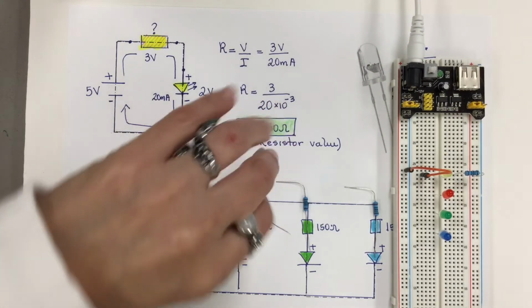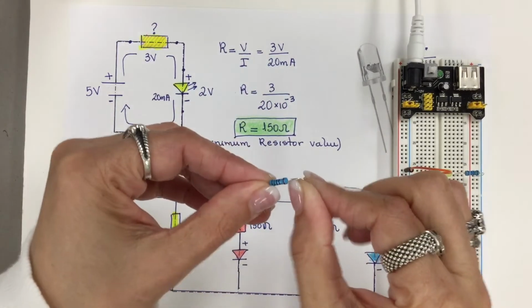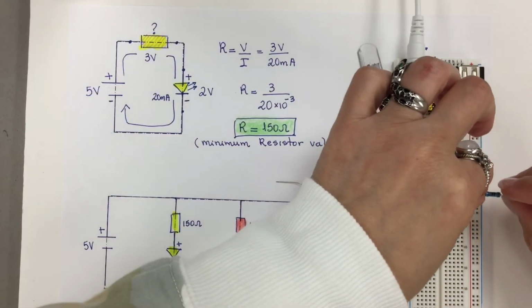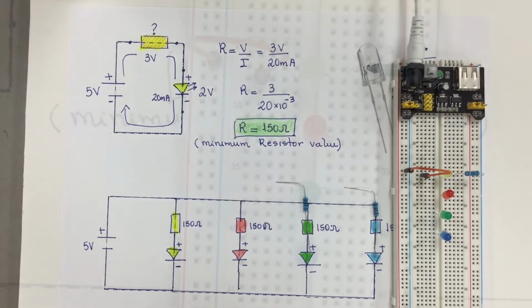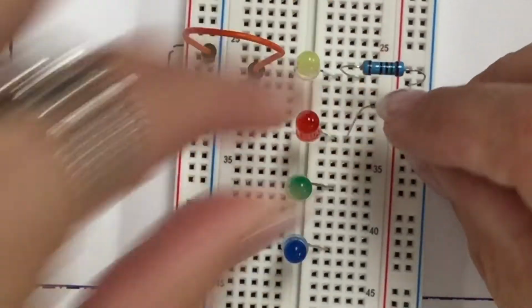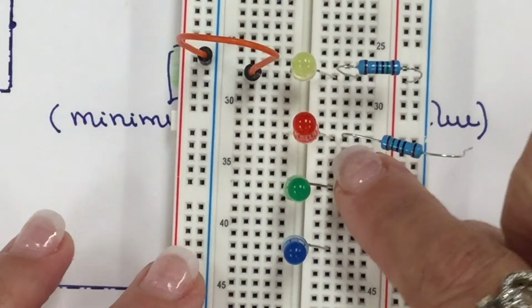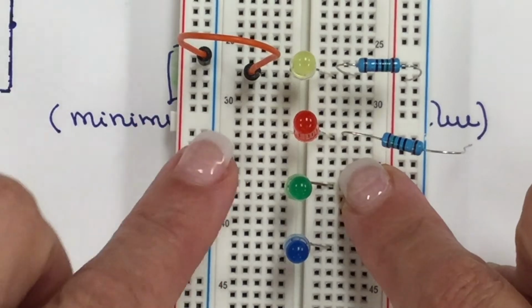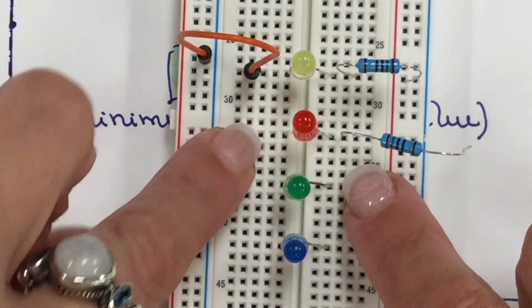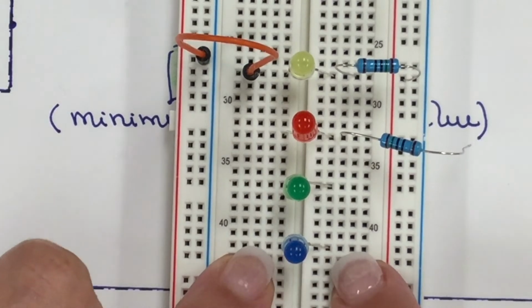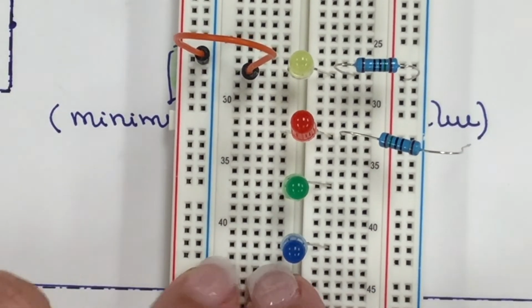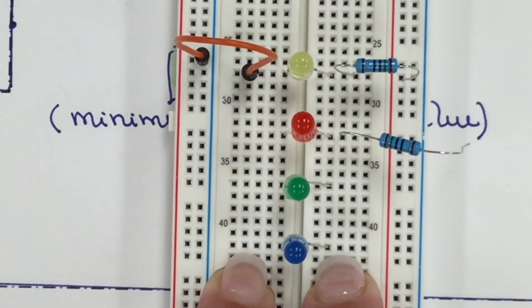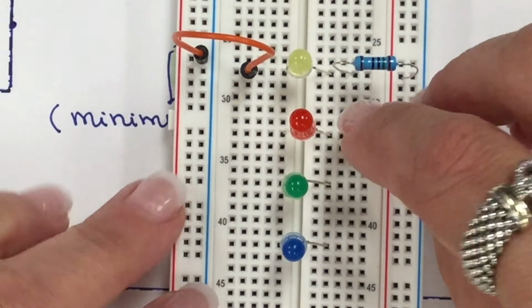So now I'm going to connect. Need to bend a little bit like this. So connect here to this. It is in series. Now remember, these sets of rows are not electrically connected to the other one, but when you use the LED, you use it like a jumper. So now you are going to connect those two rows through the LED. So now I connect here and again to the positive side.